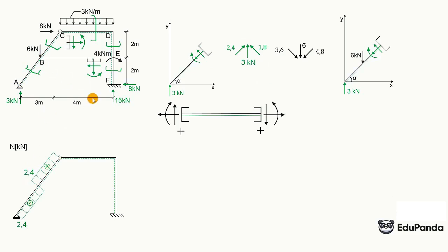And here along the entire length, there is no other tensile or compressive force than this 15. So there will be a constant value of minus 15, the opposite direction to positive, and besides, it compresses the section, which is why it's also negative. And now we'll look at the horizontal rod, but from the right side. So we cover everything on the left side of this section that I've drawn here.